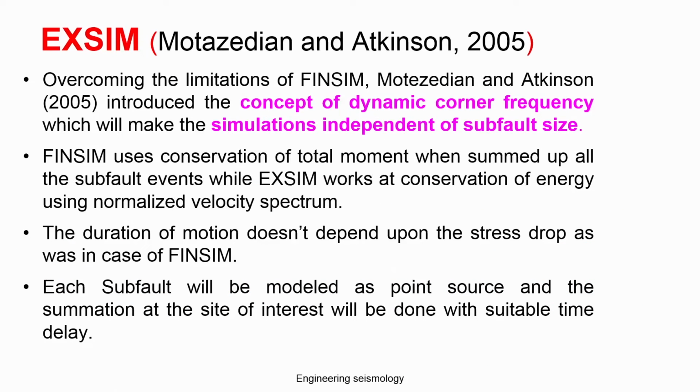So, the EXSIM, Motazedian and Atkinson 2004. In order to avoid the limitations in the FinSim model, Motazedian and Atkinson introduced a concept of dynamic corner frequency. That means the corner frequency you can keep on changing, which will make the simulation independent of the subfault size. Okay. So, now this model will overcome the subfault size issue.